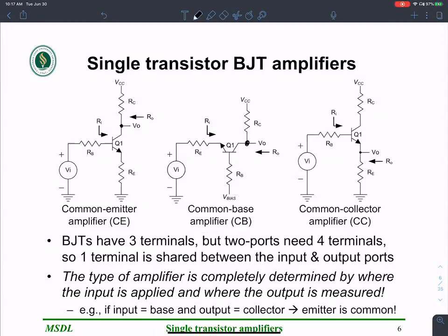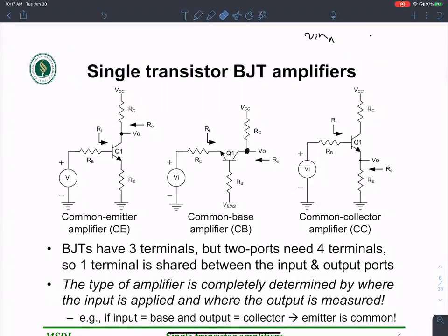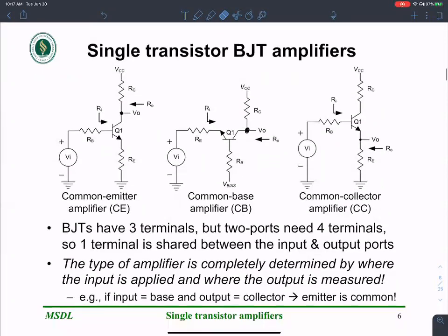So if you were to do the V output versus V input graph, it's probably going to look something like this. Up until 0.7 volts, the output voltage is below, but it's not going to be any different, just offset by 0.7 volts. That represents the forward bias voltage of a BJT. So that's this guy, 0.7.